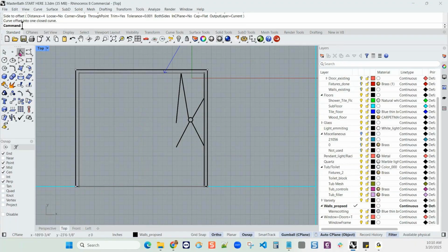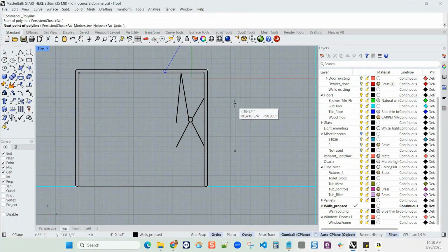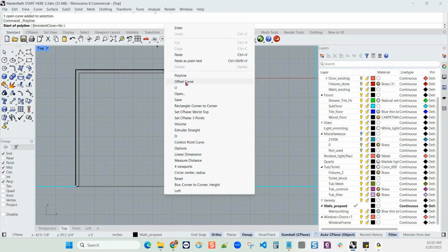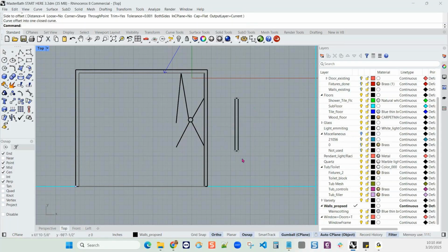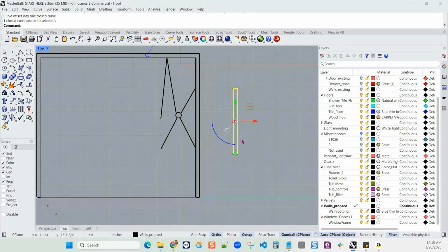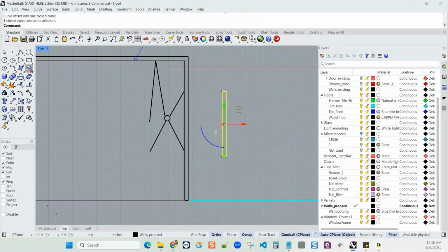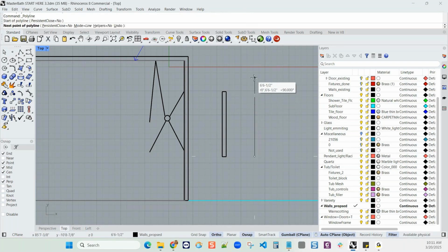But you can test out this option of cap even with a single line. If I offset it and use the cap equals flat option, I get a closed curve. Okay. And if I use, let me grab that line again. Oh, that was a control point. Edit, let me just draw another line. When I did the offset, I told it to go ahead and delete input.